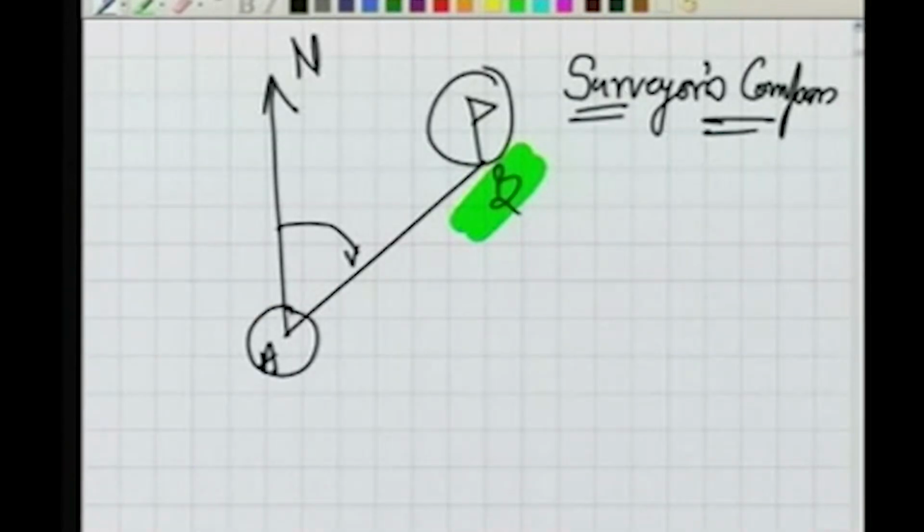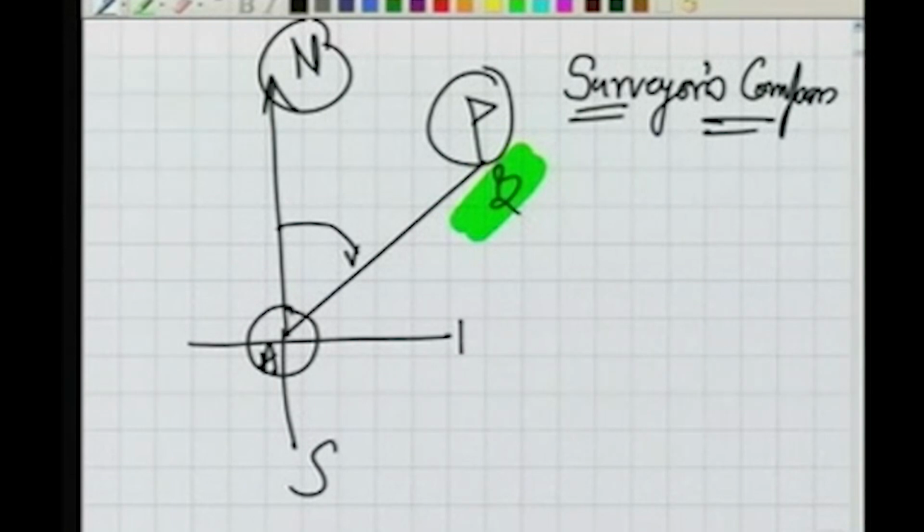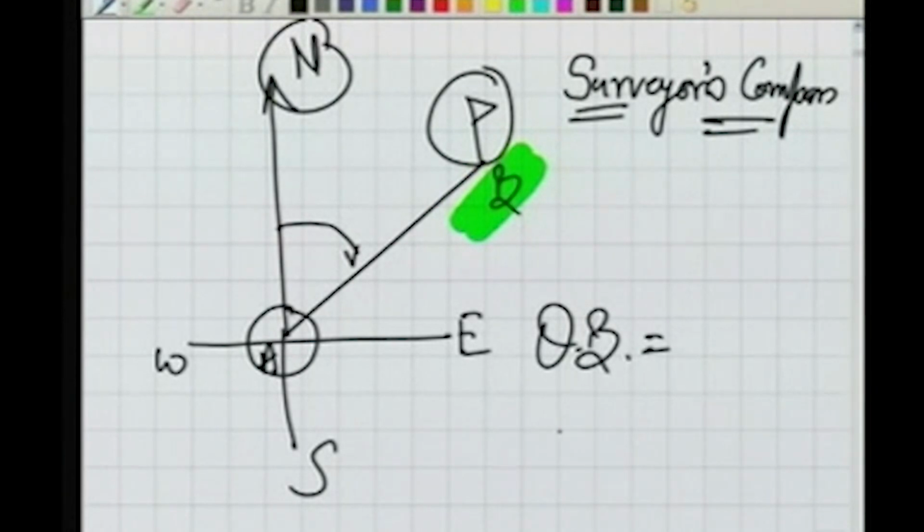What is there in the area? Well, yes, it is so. Over here, this is north, south, east and west, and in the QB system, the quadrantal bearing system, the bearing is north to east, whatever is the bearing value, and this is what we are observing here using our instrument. So now you will understand why the graduations are written in a different way. Well, the next thing which we are going to look at is local attraction.